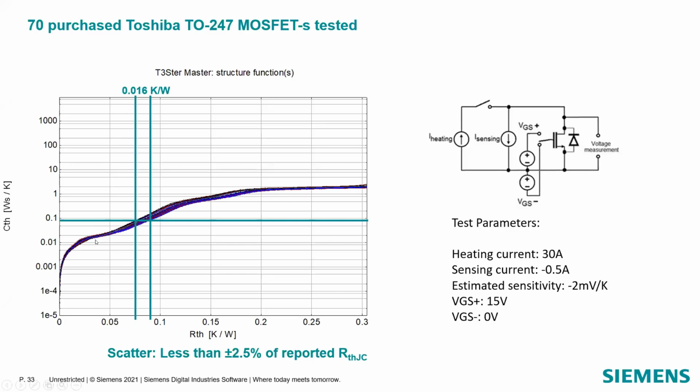So if you do this kind of analysis, you can actually make sure what you use is reliable. You're not building a component into your system which might have issues. And actually, this is a very good way to filter potential counterfeit components, because definitely they will have a different thermal signature.